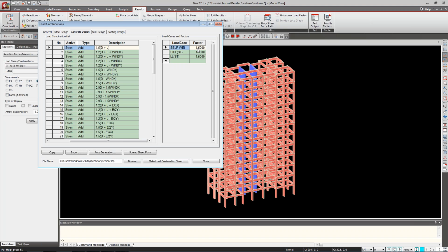According to the deflection, you can see whether it is within the permissible limit or not. If it is not within the limit, you have to introduce some shear walls. If you introduce shear walls, your base shear and these things change again. So it depends upon your structure, and the placing of the columns and the shear walls.